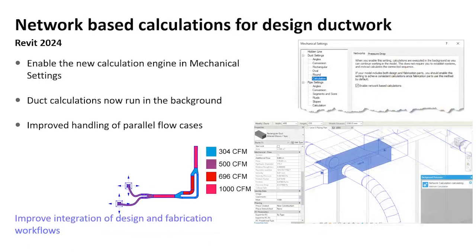We're getting more features to assist us in doing that. Speaking of that, when we want to visualize the CFM that's being generated based on the way that the ductwork was modeled, as you see in the diagram below, you can set a color fill legend based on the friction that's happening within the individual components. Well, bottom line, more integrated design and fabrication workflows for mechanical engineers.